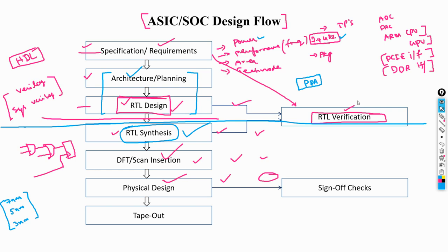Then each and every chip that we design, we will have to test. You cannot deliver them as it is. Now we add the scan and testability logic, etc. That is taken care of by the DFT team. They would decide the compression and what kind of compression and decompression architecture, and the scan chain information and how many flops per chain. So the DFT team will decide.